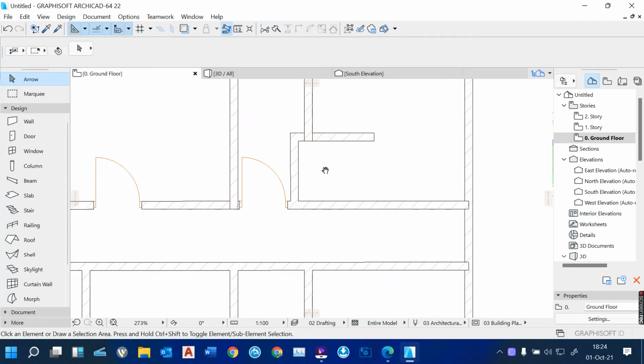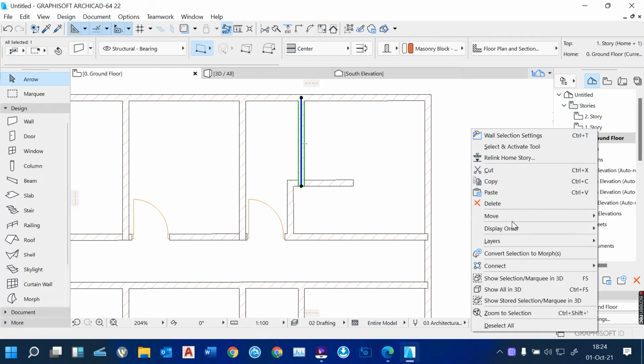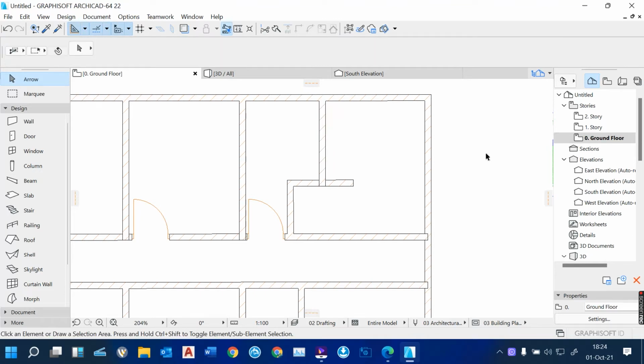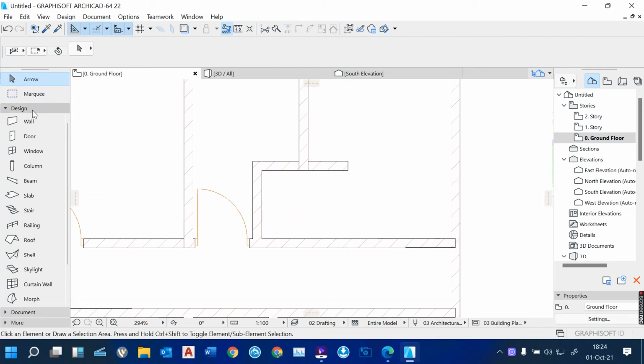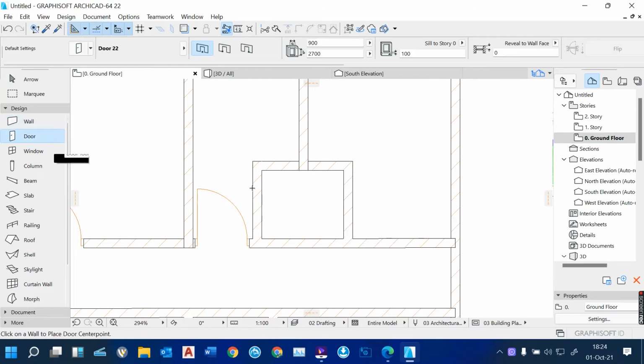And you can see it going. So we can move this by dragging. You can simply now drag, because we are not dragging a copy. It's up to 500. So we leave that space, and then now you pick your wall and place your door. And then I place my door here, for that entrance.